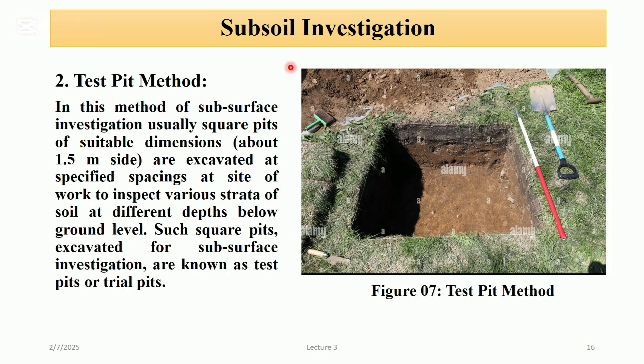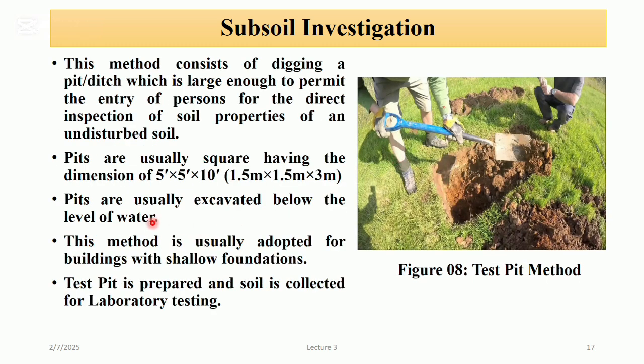Test pit method. In this method of subsoil investigation, we excavate a square pit of dimension 1.5 meter by 1.5 meter, and the depth should not be greater than 3 meter. At depth we inspect the strata. This method is used only for foundations having depth not greater than 3 meter, because the excavation of a test pit is comparatively costly. Pits are usually excavated above the level of water.